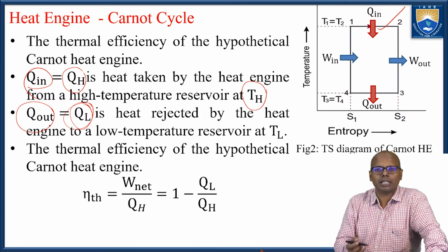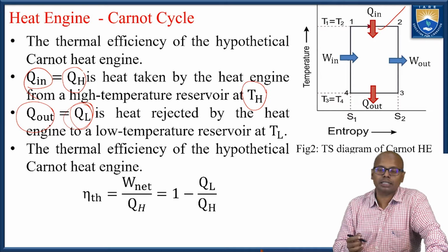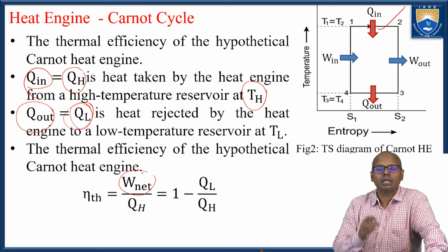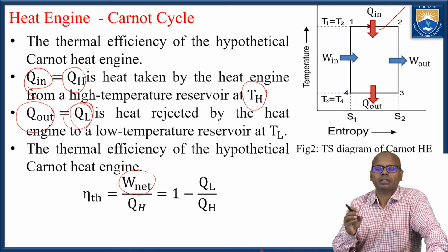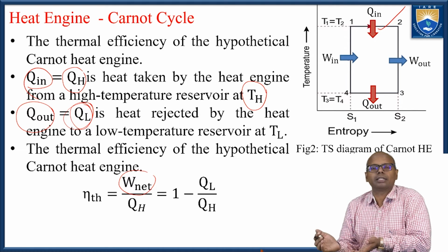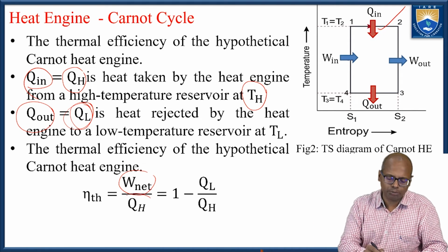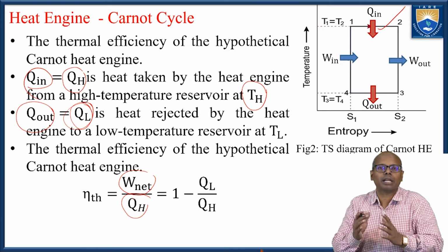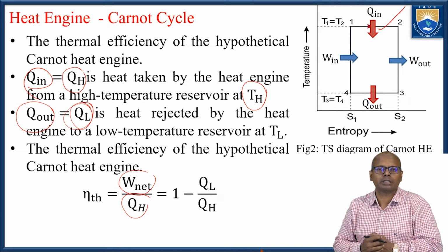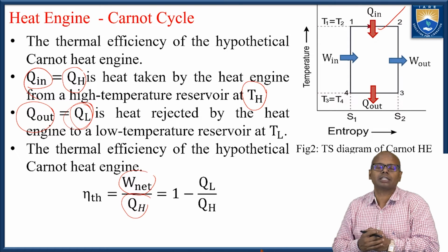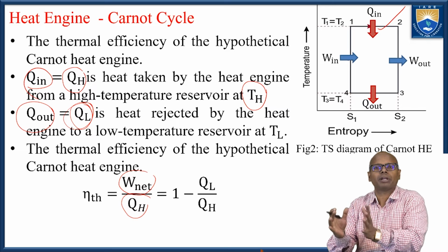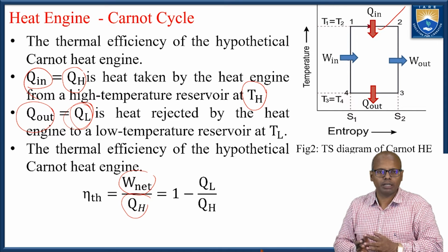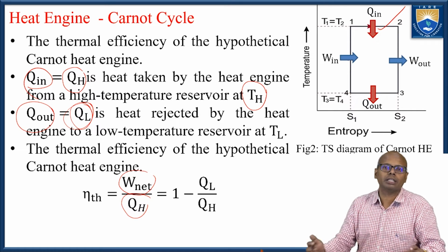Now what is efficiency? What is the main purpose of this engine? I need net work. Some work output should be there for the Carnot engine, and the net work is the desired output, and the input is the heat supplied by the high temperature reservoir. So the thermal efficiency is equal to the net work supplied by the heat engine divided by the net heat taken by the heat engine.